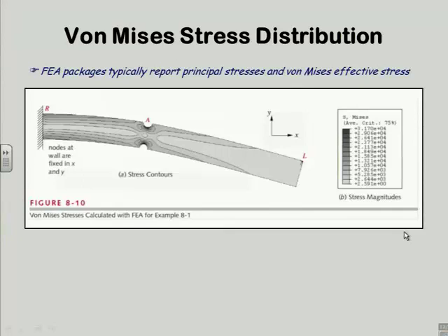I have a question. For the notch, if the notch is triangular with sharp edges, and you refine the mesh by increasing the number of elements, the stress just goes to infinity. It doesn't converge. So I still don't know how to do that. If it's triangular. A triangular notch. Oh, now I understand what you're saying. He's saying if I have a triangular notch, a real sharp notch, the stress at the corner is infinite, right? And the thing will blow up. So I think you have to probably fake it and round it off a little bit, because you can't let the stresses go to infinity. The computer won't deal with it.